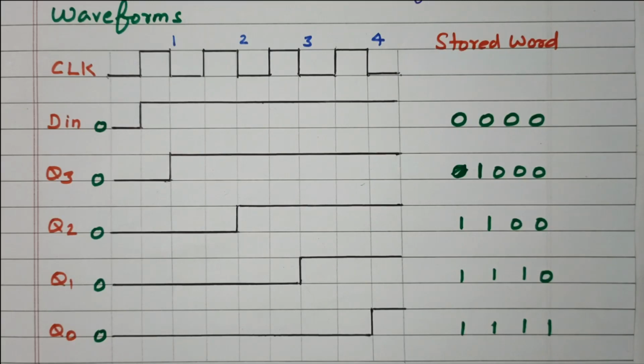When 1 is applied, the output of the flip-flop is 1. When 0 is applied, the output of the flip-flop is 0. So the data we require is passed to the input of the flip-flop. The same data is available at the output, because in a D flip-flop the output next state depends upon the D input. D input will be reflected as the next state. Then we discussed how the data is moving in the basic block diagram. We discussed the truth table and waveform also.